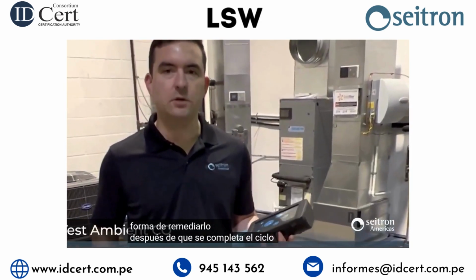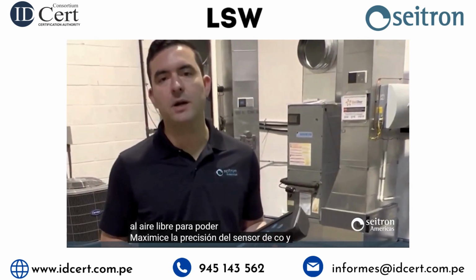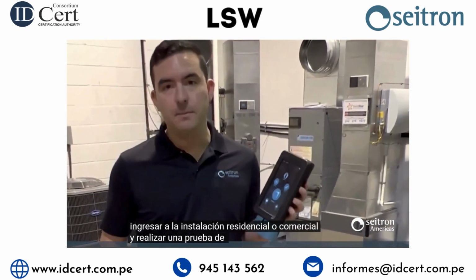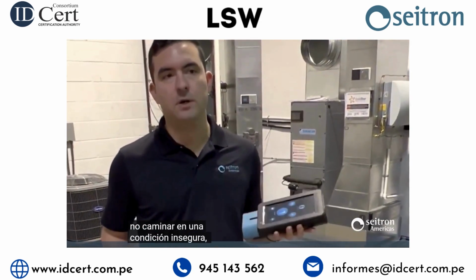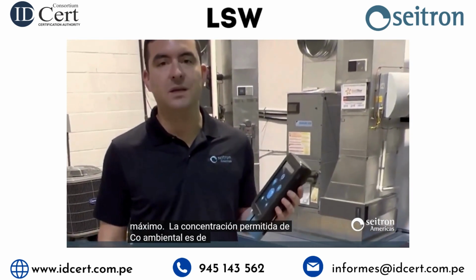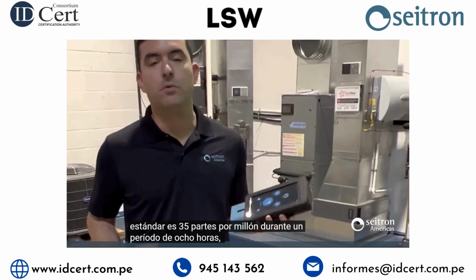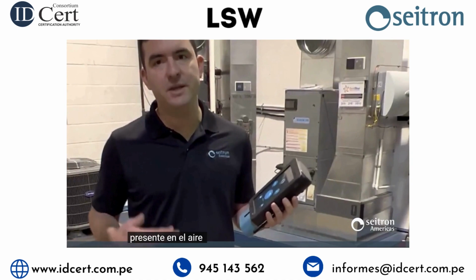After the auto zero cycle is completed outside in fresh air, in order to maximize the accuracy of the CO and oxygen sensor, the first thing you do is walk into the residential or commercial facility and test for ambient carbon monoxide levels. You want to make sure you're not walking into an unsafe condition. So the ASHRAE standard for the maximum allowable concentration of ambient CO is 9 parts per million over a 24-hour exposure. The other standard is 35 parts per million over an 8-hour period. But in reality, there should be 0 ppm of ambient carbon monoxide present in the ambient air inside a building.